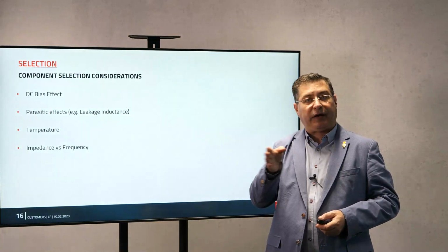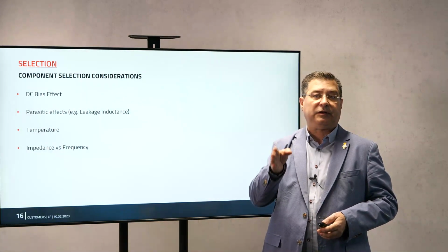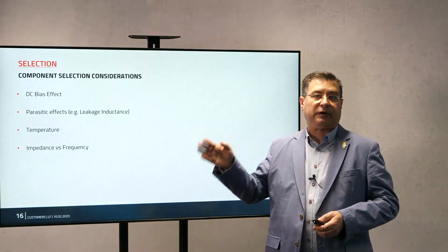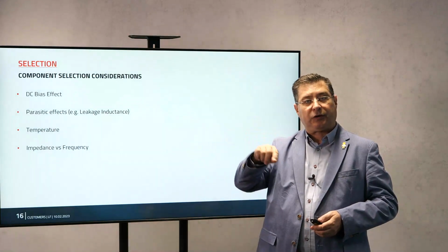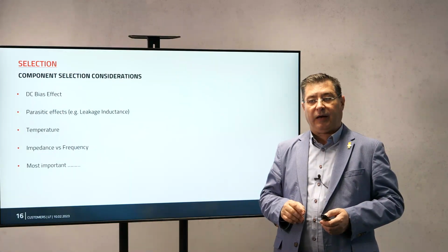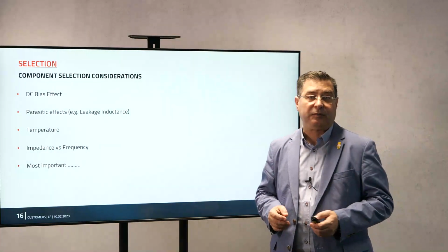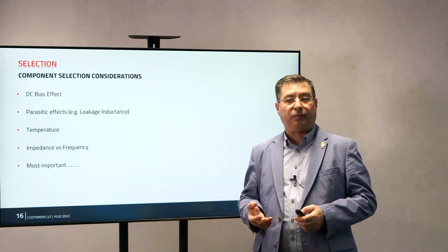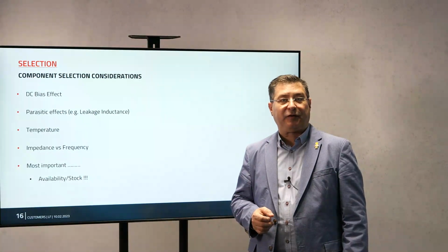Look on your spectrum at which frequency you need this impedance, and don't choose only because of 100 megahertz. Choose according to the impedance curve, to the frequency, to the right position. And the last thing, the most important today, if you select components which are available from stock.